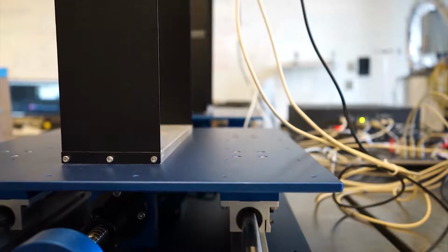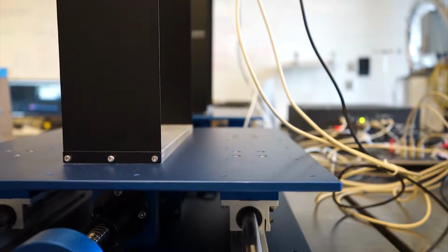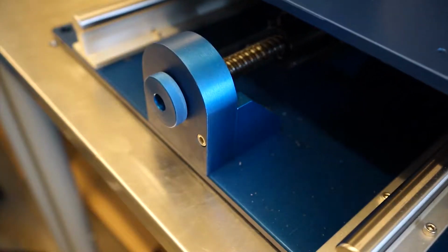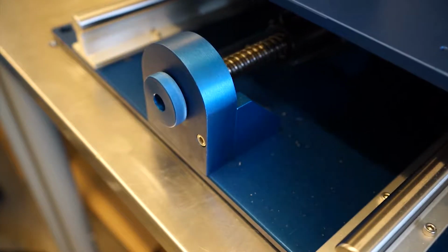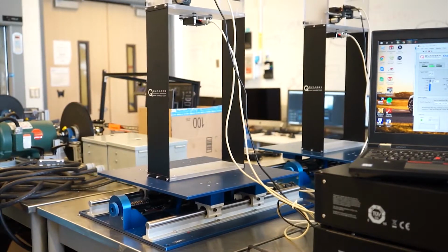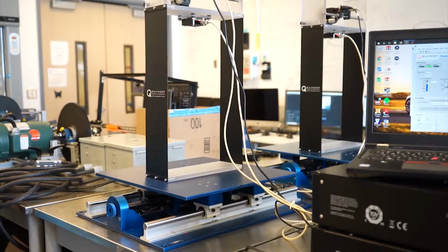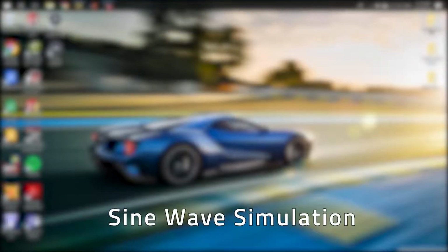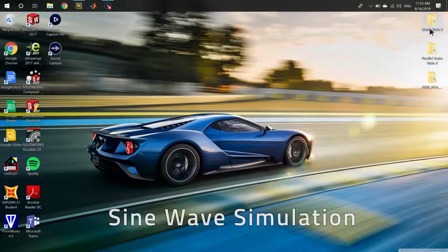Tabletop shake table setup can be used to demonstrate and investigate the effect of sinusoidal, vibrational, and seismic movements for different materials and scale models. When calibrated correctly, the shake table can simulate scale positional data of various acceleration curves in a very accurate manner. It can also be set up to test longitudinal and transverse motion.